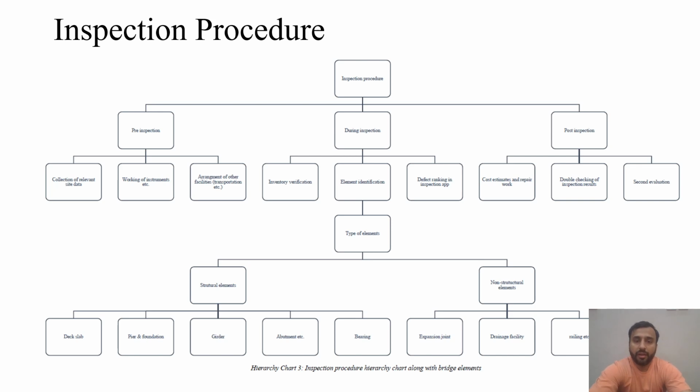In the case of element identification, different elements, structural and non-structural, will be inspected, and photos from different angles are required to be registered in the bridge inspection application.